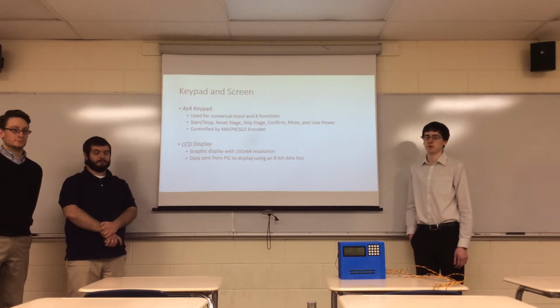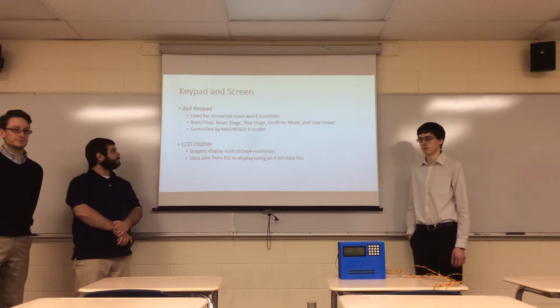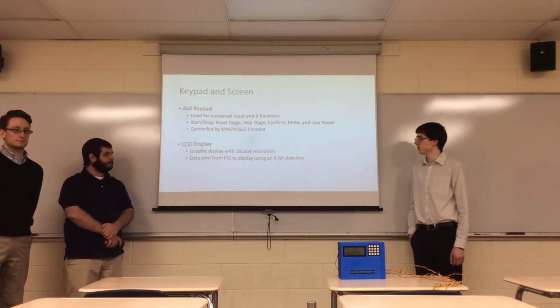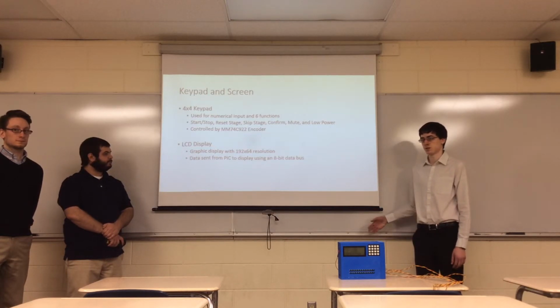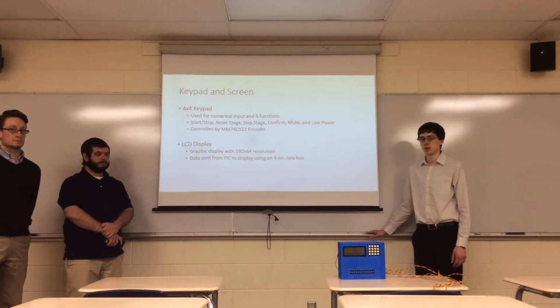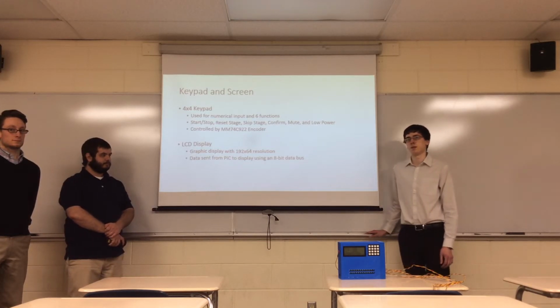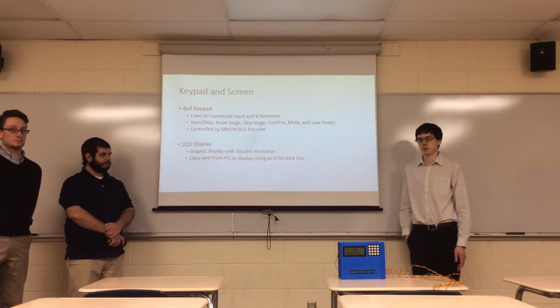The display uses an 8-bit bus to receive data. We write to it using commands all written in the PIC, complete with a few commands to draw different things, including pixel by pixel or rectangles, and we have both digits 0 through 9 and capital letters A through Z.